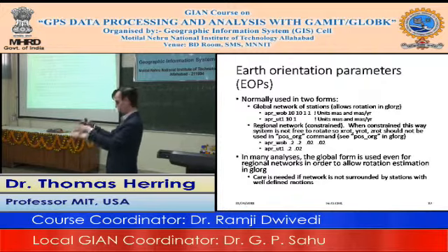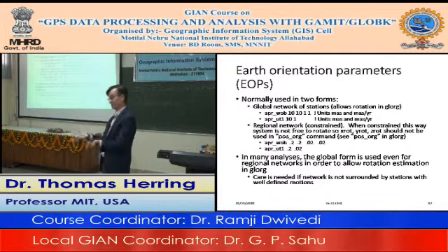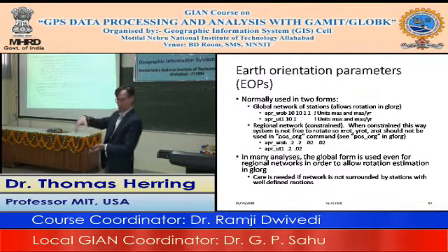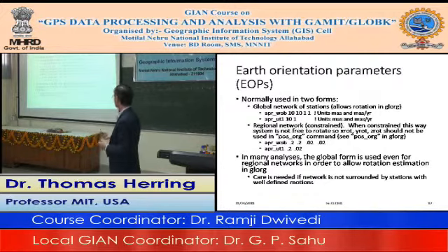let it rotate. And again, it's a subtle issue of the Earth orientation parameters we have are the whole Earth orientation parameters. And when we have these common mode errors across regions that we want to remove, that common mode error can be represented as a rotation and translation. And so we allow a rotation, which is bigger than the rotation for the whole Earth. So again, our recommendation is to stick to this sort of wobble number and do the rotation in GLOBK.